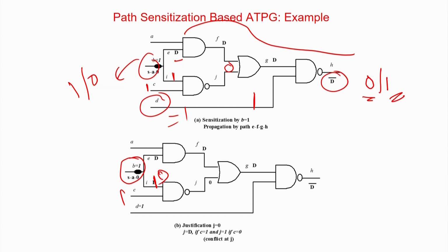Now it is a 3-level circuit, in this case it will be a very high level. This level means I am talking about these levels, this is 1, 2, 3, 4 level circuit. It will be a more higher level circuit and things will again blow up because the number of stuck faults will be higher. Sensitize, propagate, justification will be difficult because there will be so many alternative paths to try and so forth. So there the optimization will be at a higher level of test, that is not even at the gate level, even at the black box level, like adder. I will consider adder as a block. I will consider maybe a multiplier as a block. This is actually called RTL level test.